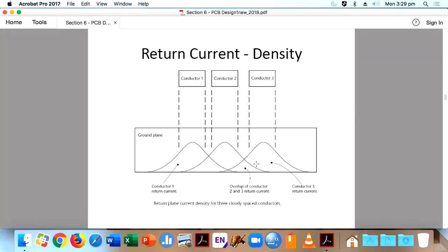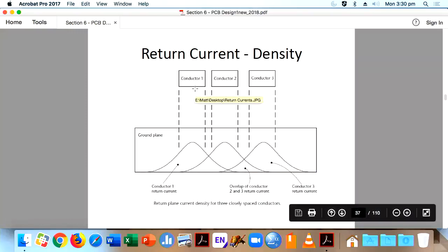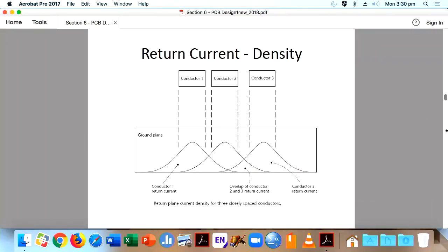Then another aspect is when you have your PCB. On the PCB, on the top layer, you see the copper track, that is your signal. And then you got a material here called FR4, a dielectric material, FR4 for low frequencies. If you are designing high frequency boards in gigahertz, you will be using a material called Rogers board. But you will mostly see FR4. Even for your DSO, you will be getting an FR4 board. So then you see the copper track here, then you got the FR4, then you got the ground plane.